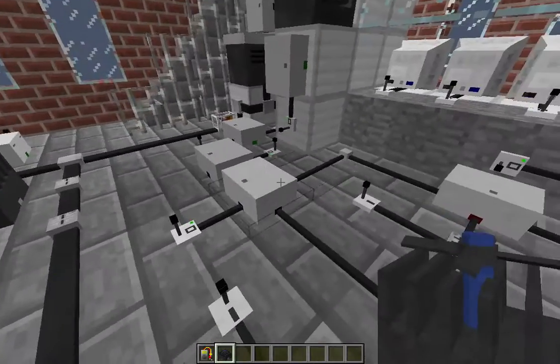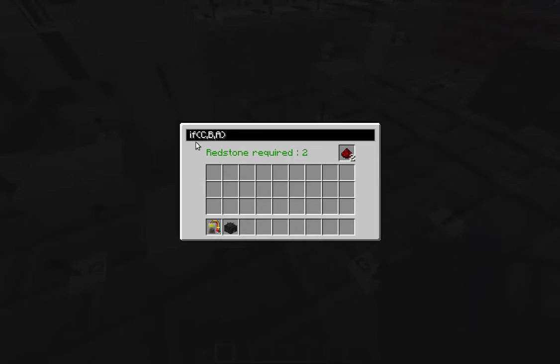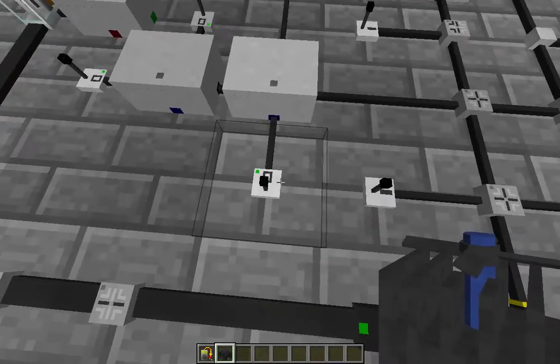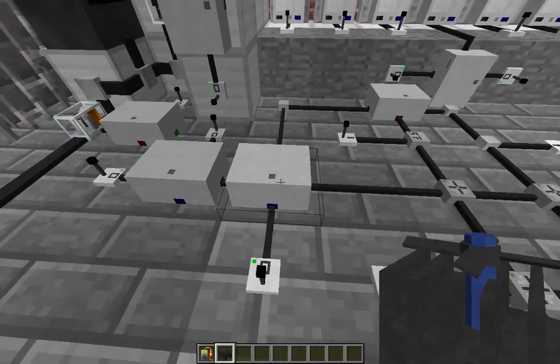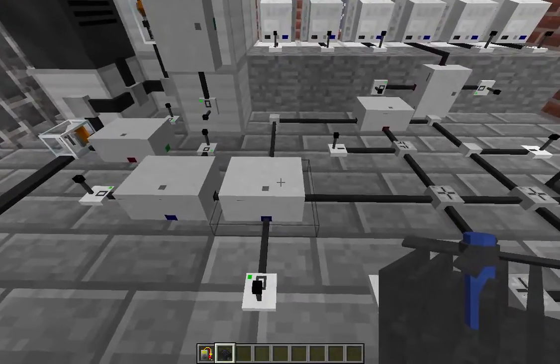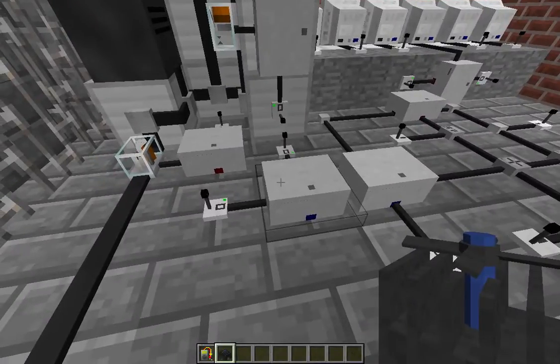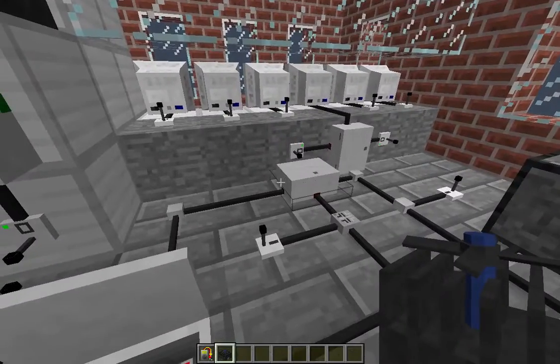Now this junction box here is a unique twist, in that he has an if statement. So, if C, use B, otherwise use A to control your furnace. This is simply a relay to the override switch, so if the override switch is on, control the furnace using this box. If the override switch is off, control the furnace as we normally would.